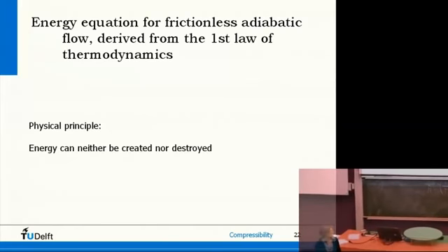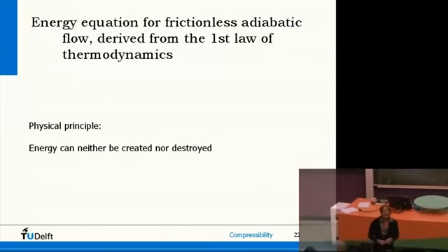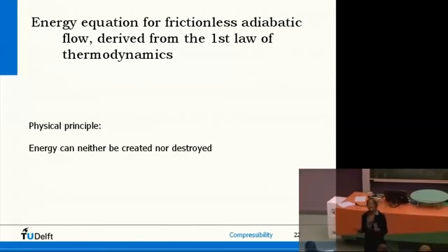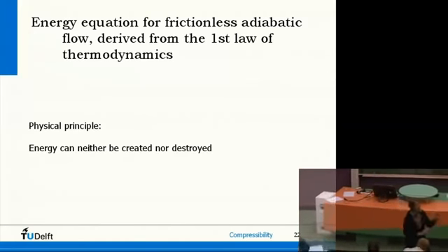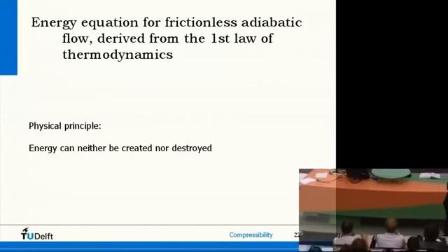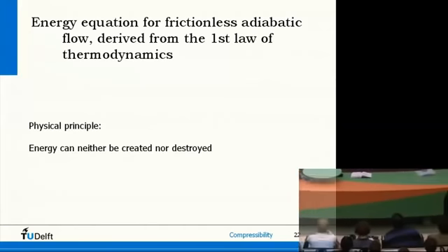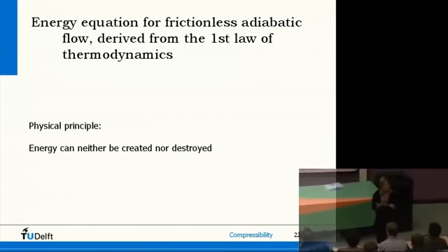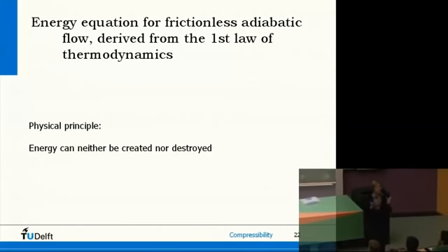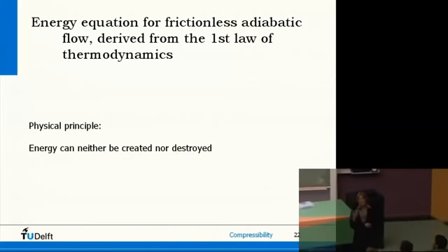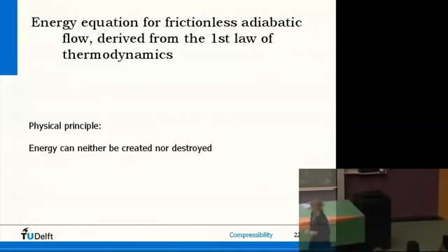Now the last step for today. Nice, we have relations between scalar quantities, right? For isentropic flow: pressures, densities, velocities. But for compressible flows, we have no ideas of the speed. We have Bernoulli for incompressible flow. We have the Euler equation, of course: dP is minus rho V dV. But what do we do for compressible flows? We have the energy equation. And that's what I'm going to derive, make an example with, and then that's it.